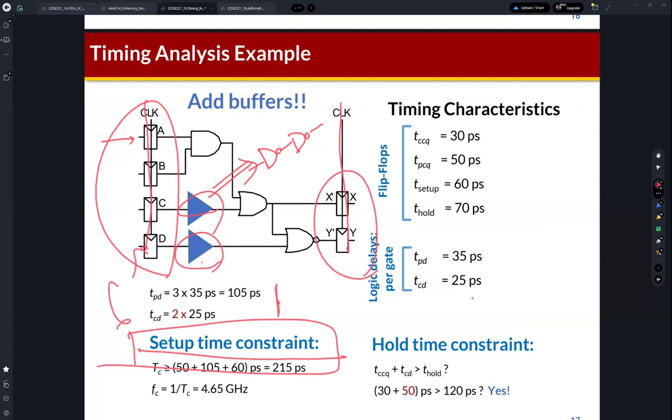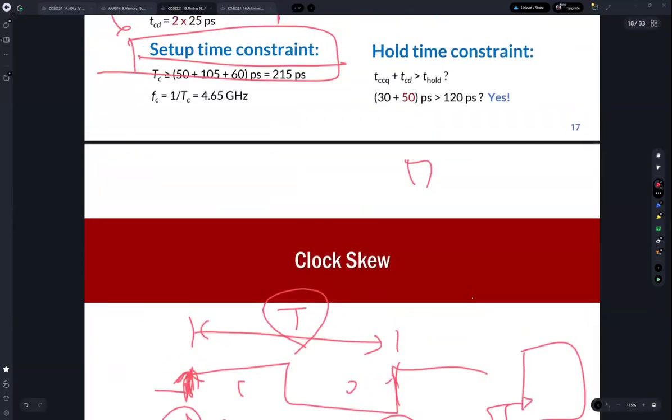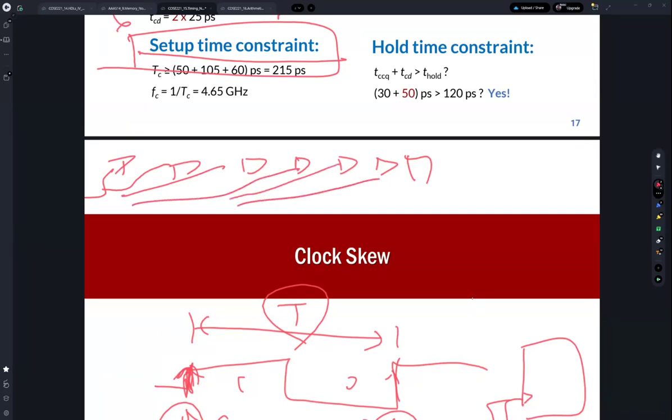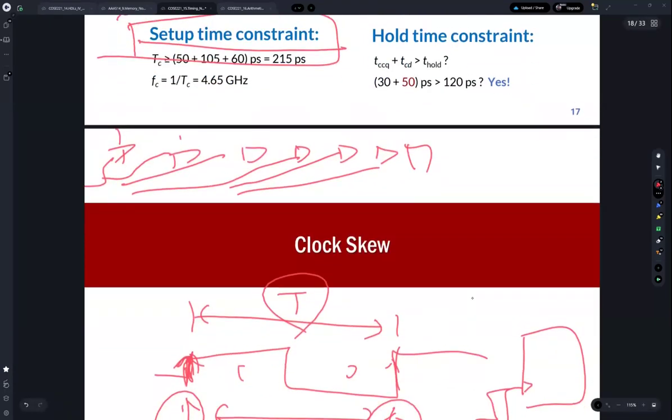Okay, so it means there is delay. Clock signals are delivered to many D flip-flops, but because of wire delays, the timing of this clock signal for individual D flip-flops can be different. Okay, so ideally, there are many D flip-flops, and clock signals are connected to every D flip-flop, right? So ideally, the timing of a rising edge for these D flip-flops needs to be the same.